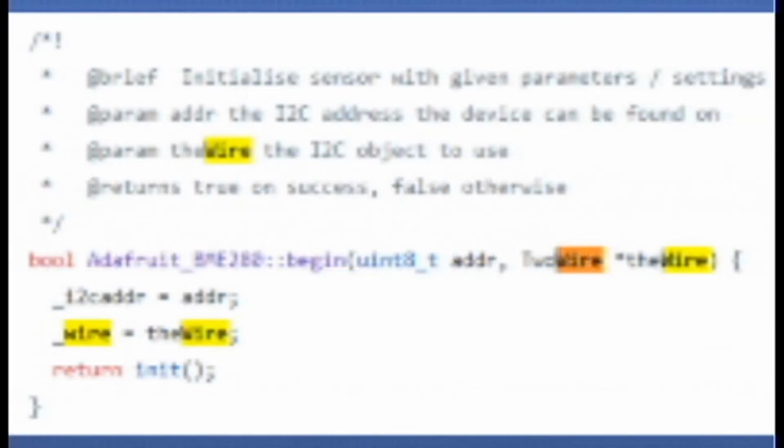So, you just need to set your desired SDA and SCL GPIOs on the I2C_SDA and I2C_SCL variables. However, if you're using libraries to communicate with those sensors, this might not work and it might be a bit tricky to select other pins. That happens because those libraries might overwrite your pins if you don't pass your own Wire instance when initializing the library. In those cases, you need to take a closer look at the .cpp library files and see how to pass your own TwoWire parameters.